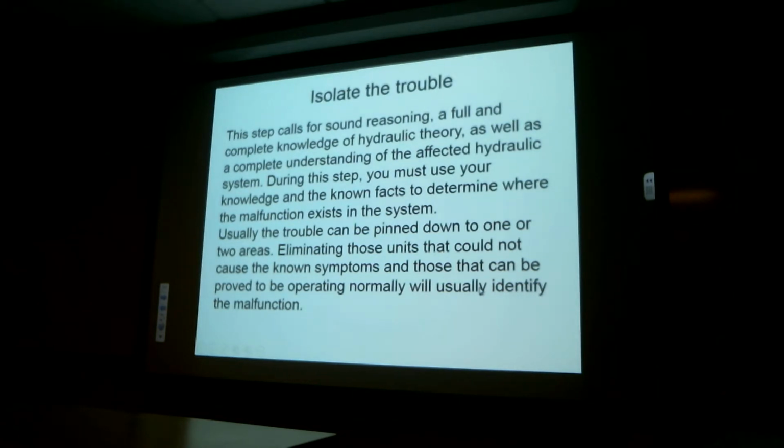Well, you know from a lot of hydraulic systems, if you've got a low reservoir, the hydraulic pump is starved of fluid because of the standpipe that's in the reservoir. So if that particular circuit is operational using the hand pump, really the fix to that kind of problem is nothing more than adding fluid and replenishing the fluid in the reservoir. And miraculously, the problem is solved.